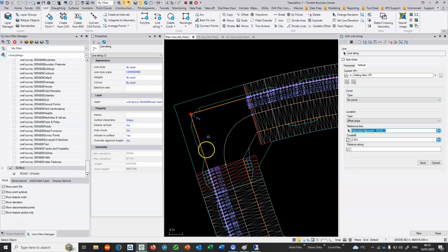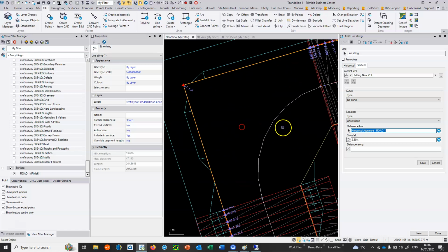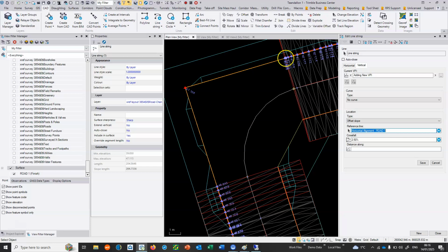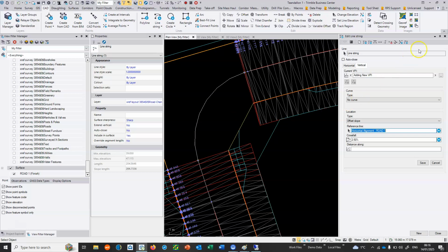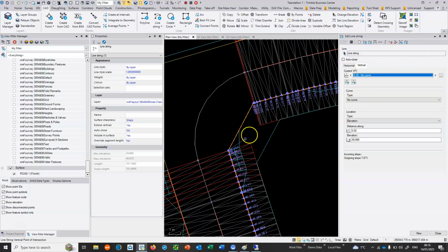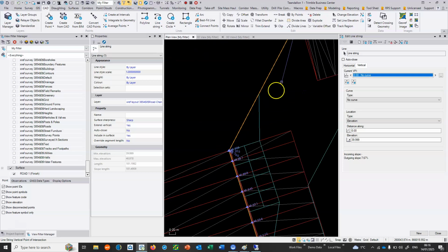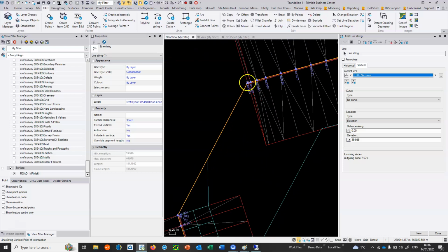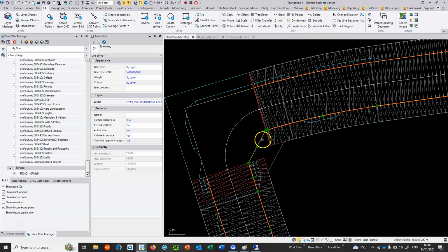And you can see that's what it's basically done, is it's taken from the centerline string a separate height to positive 2.5. So there's going to be a set grade going along this line here and a set grade going in here. On the inside, because this is relatively short, I'm not going to add anything here at all. So if we just select the string, so we can see where we've got height levels here, and we've got levels here that are coming from the road design, and we've got a set transition going through there, which looks reasonable.